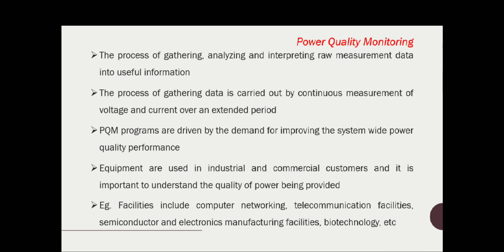What is power quality monitoring? Power quality monitoring is the process of gathering, analyzing, and interpreting raw measurement data into useful information. The process of gathering data is usually carried out by continuous measurement of voltage and current over an extended period.